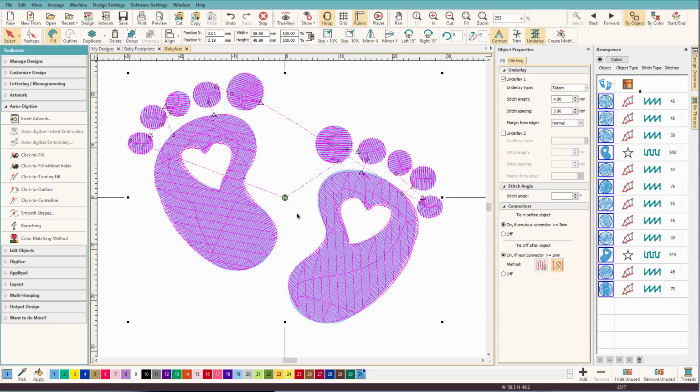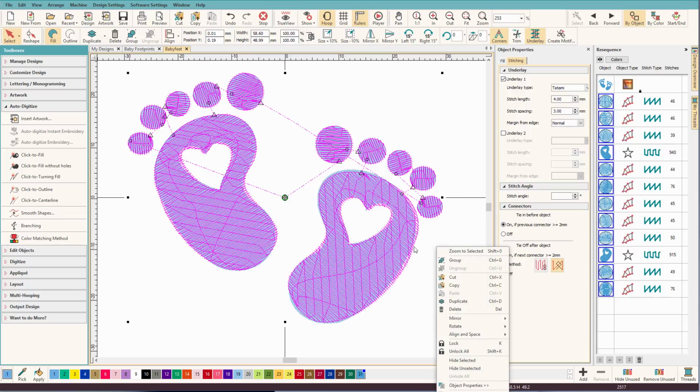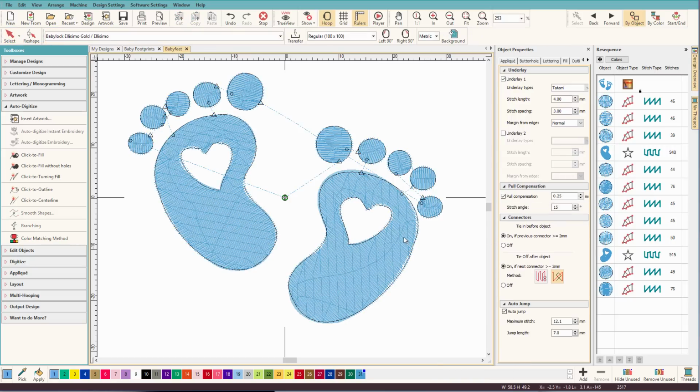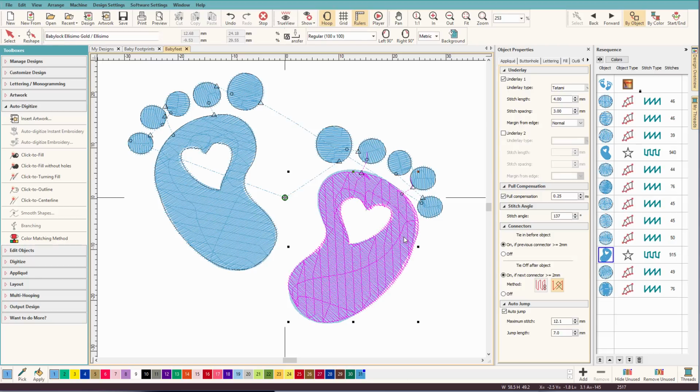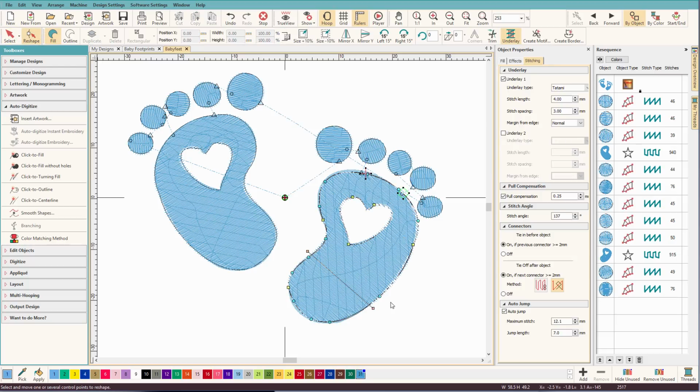And what that does is it kind of softens the lines. You can see it doesn't quite follow the shape perfectly, but no one's going to see this artwork. You're the only one seeing this artwork as you digitize it. And now if I select this shape, press H, there are fewer nodes along these shapes. It just makes it smoother. So if I want to adjust it, it's easier for me to manually adjust it if I wanted to do that. And you just adjust it by clicking on one of those nodes and dragging it in or out.